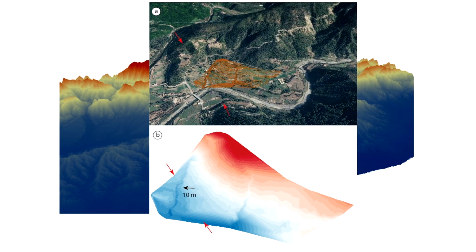This is an instrument with the help of the GPS, the rover and base antenna, you can acquire the elevation data from the earth surface, and you can process those elevation data on the GIS platform and generate the DEM. So here you can see this is a high resolution DEM which is prepared with the help of RTK.